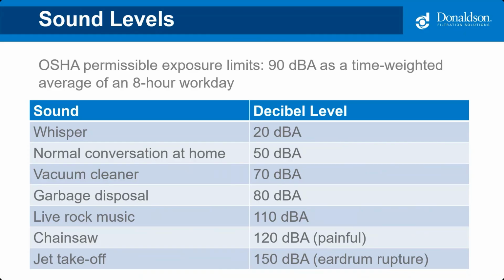If I'm deciding between a few different fan options, sound is definitely something I take a look at. The quieter the better, and oftentimes I specify a sound silencer to help reduce it further. But I always try to stay below 85 dBA, which often does require a silencer.